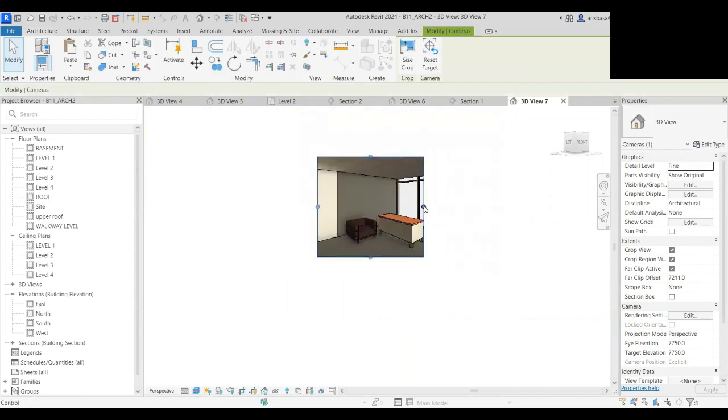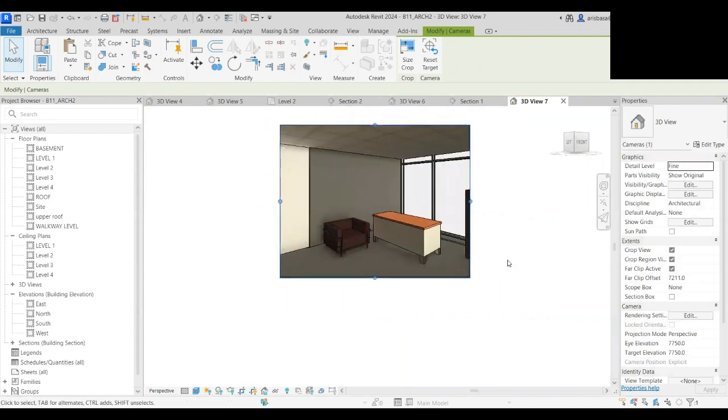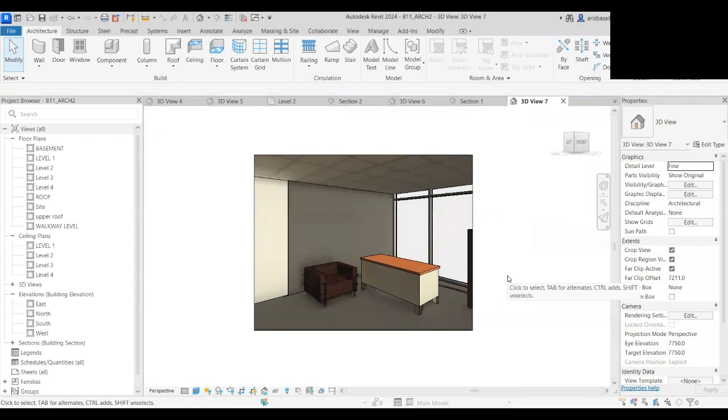So that is Razak's security office, construction office. You want to render interior? We have time, no? But the problem is, if you render interior, you have to make sure that you have windows so that there will be a source of light. Because if you render one room like this without the light, it will totally be black. You won't see anything. You keep waiting and you'll not see anything. That's just what happened to me before when I was a beginner. I was waiting and nothing was coming.